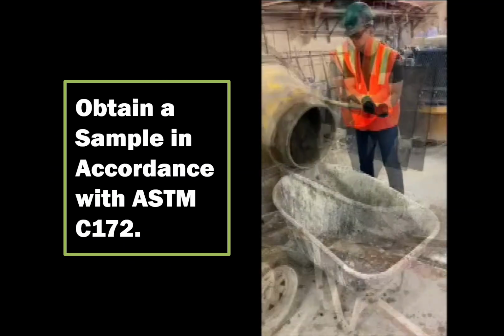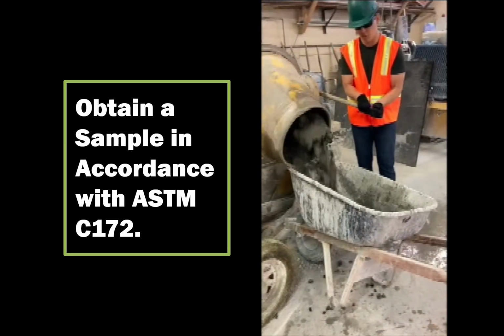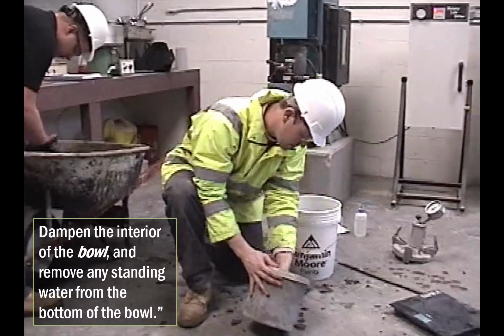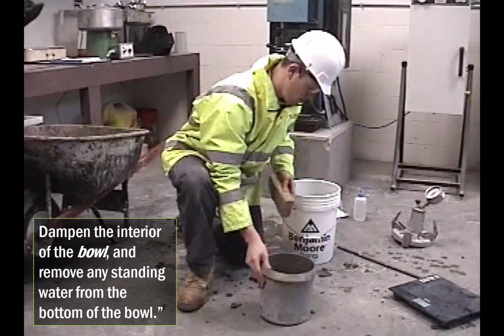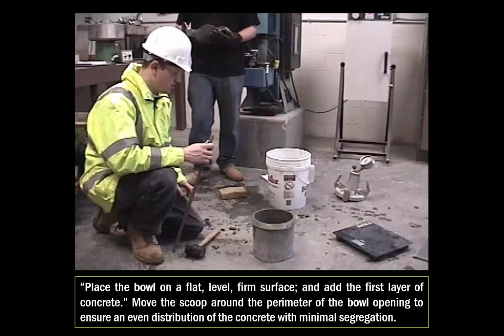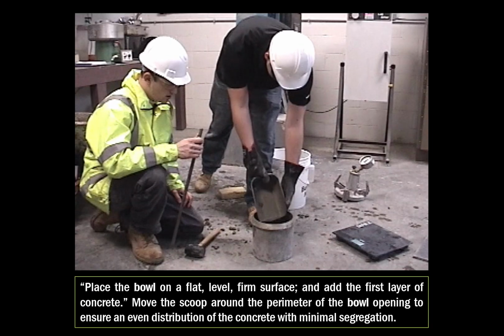Obtain a sample in accordance with ASTM C172. Dampen the interior of the bowl and remove any standing water from the bottom of the bowl. Place the bowl on a flat, level, firm surface and add the first layer of concrete. Move the scoop around the perimeter of the bowl opening to ensure an even distribution of the concrete with minimal segregation.